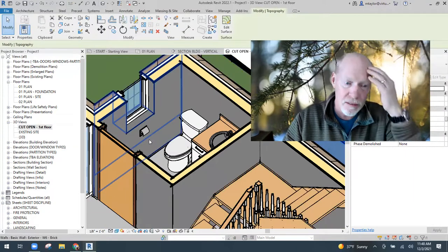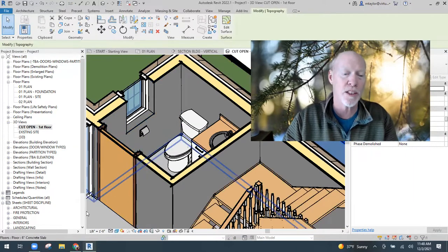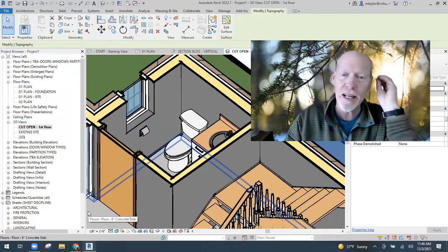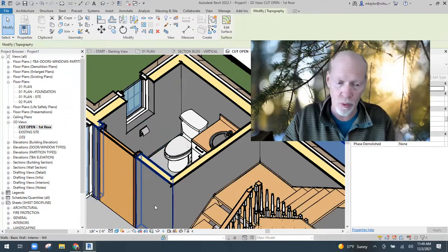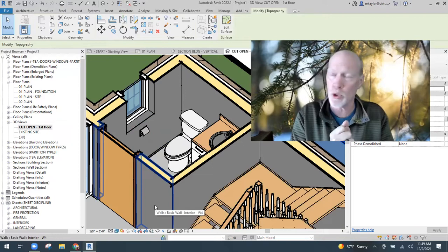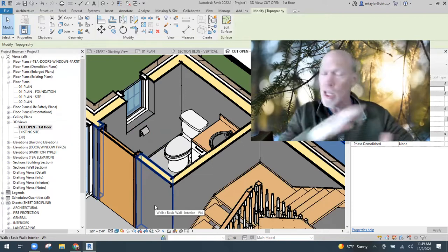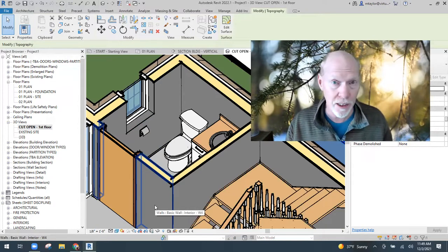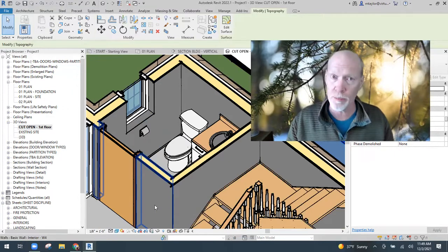It has been designed well, even though it was built in 2010. They made it out of true geometry from Revit. If you can get true geometry, you should always open your families, look them over and see what you're dealing with before you bring them into your project. Don't just grab them and jam them in. Open them up and look at them.